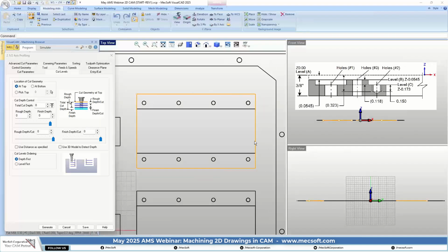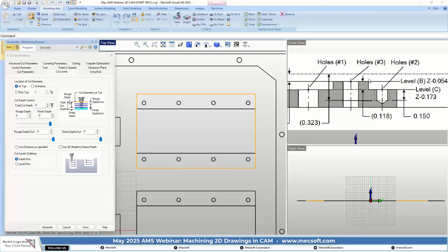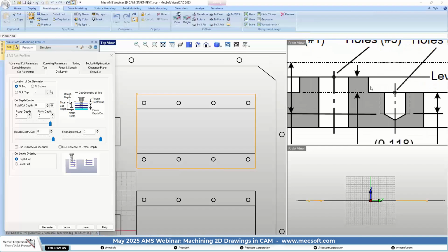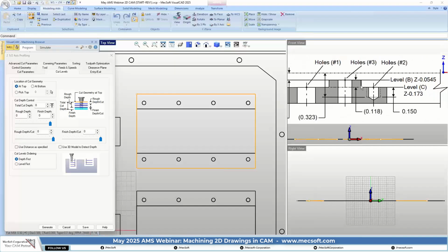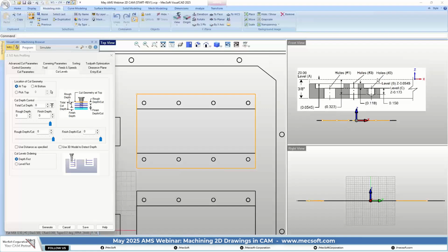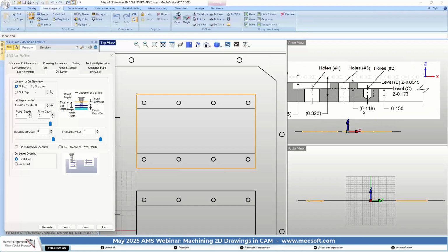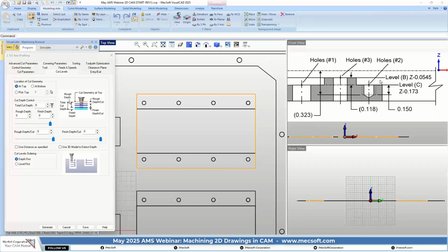This area we're cutting, okay, is a profiling operation, and it's cutting along this edge right here. Okay, you see this edge? And this edge, and it extends out past this edge. This is that edge, outer edge, inner edge right here. And these holes are the drill and tapped holes right here. Okay, so the section view only does one side of it. You don't see all of it, okay? So the start of the cut, again, is going to be at the negative 0.545 because we already have it machined down to that cut level.